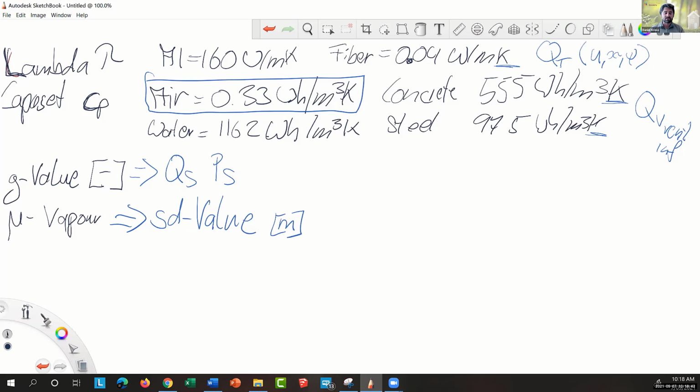At the end, the solution for passive houses is heat pumps for domestic hot water and for heating and cooling. The limitation of heat pumps is the thermal difference of 60 Kelvin that we have. So if the temperature drops below minus 20 degrees, then we have the problem that the heat pump doesn't work any longer. And then probably burning something, a liquid fuel or a gas that we can burn, is the right solution for a really cold climate. So we have to keep that in mind. And then there's the limitation of the noise a little bit.